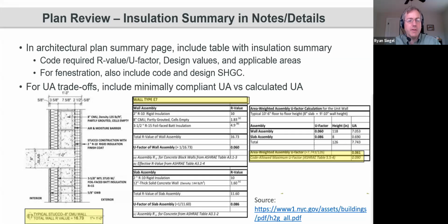And here on the left, as you can see, we have an illustration showing a wall assembly cross section. And in this one, we're using insulation both on the inside and outside. So providing that good thermal break with that continuous insulation on the exterior, along with some cavity insulation on the inside for additional insulation. So having that thermal break is very, very important and very effective as far as helping to reduce comfort issues, particularly at the perimeter of walls.